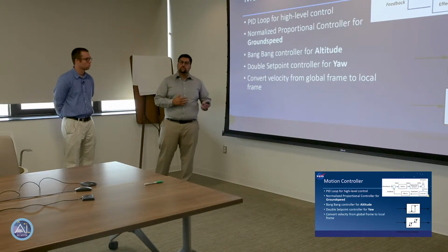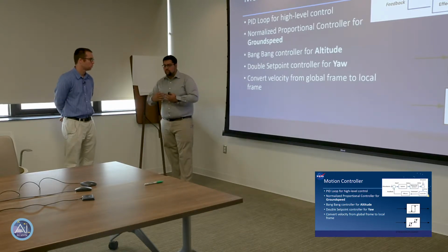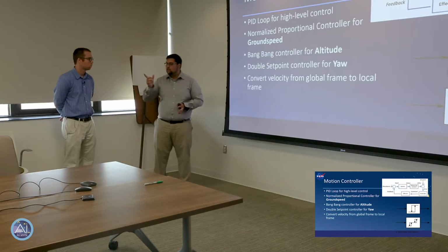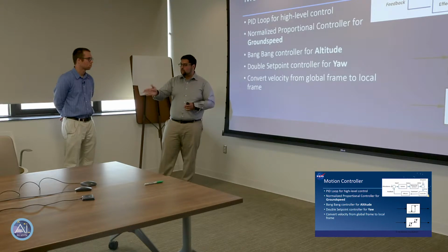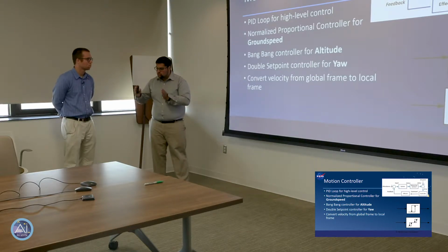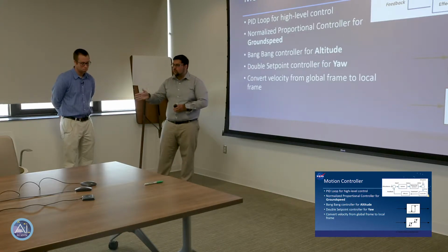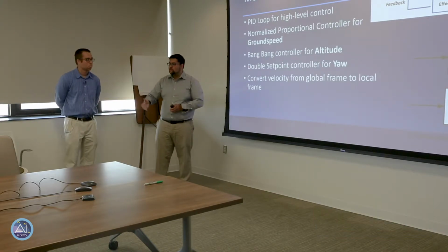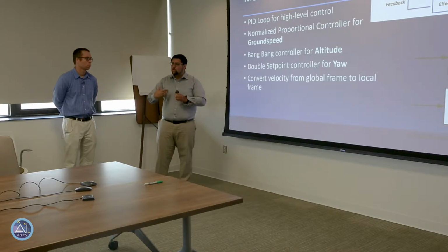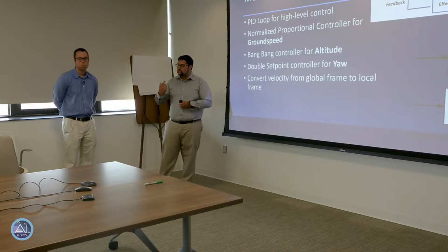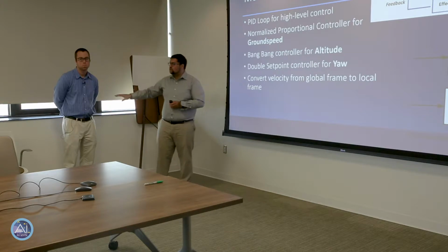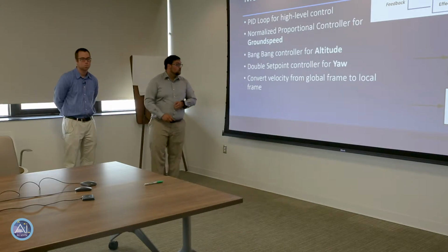The reason we did that is because when the drone starts, it's obviously not pointing the right way. It needs to get to the right point of view fast. And so it moves really fast to focus in on the cylinder. And then as the drone is slowly moving around the cylinder, we don't want it moving fast again, trying to re-localize itself. So we apply very subtle changes to the yaw to make sure the transition is as smooth as possible and doesn't interrupt the video stream.